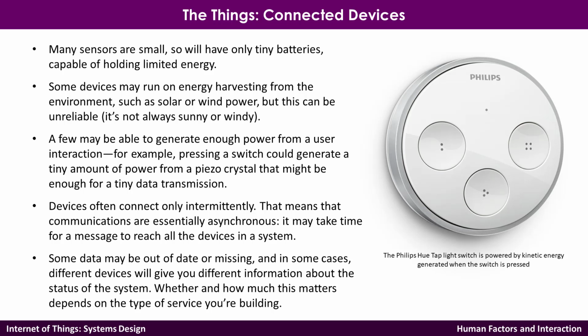You also need to think about how you are going to report the battery status or energy status, or whether you need multiple battery sources or multiple power sources, like having direct power and a backup battery. For example, with critical things like fire alarms or other security systems, where you have the main power, if it is somehow disconnected, then the backup battery kicks in for at least some number of hours, so it can maintain the security or the mission-critical process.